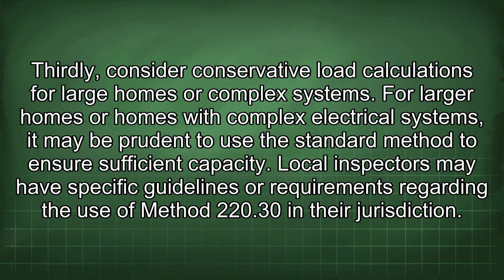Thirdly, consider conservative load calculations for large homes or complex systems. For larger homes or homes with complex electrical systems, it may be prudent to use the standard method to ensure sufficient capacity. Local inspectors may have specific guidelines or requirements regarding the use of method 220.30 in their jurisdiction.